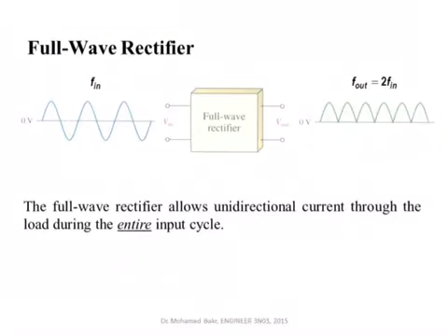The circuit that does this takes an AC signal and creates this rectified signal. And this signal, by the way, has double the input frequency, because this one had a frequency of 60 hertz, so this was one complete periodic time, while for this one, this is a periodic time. The periodic time is now dropped by half. So this one has double the frequency. The frequency for this one here is 120 hertz, say.